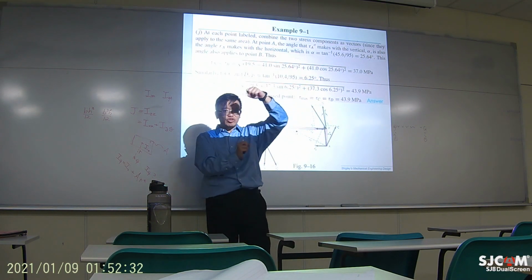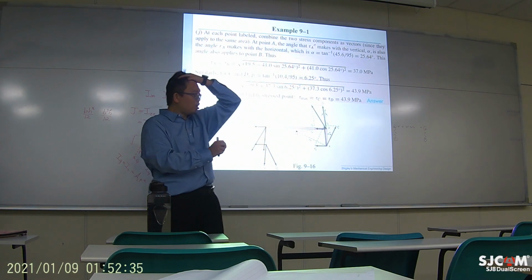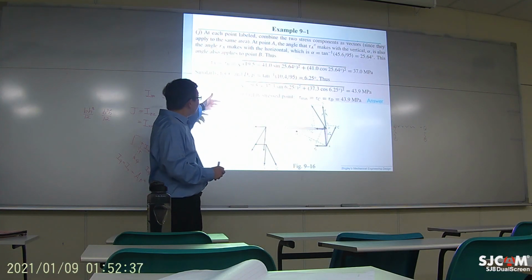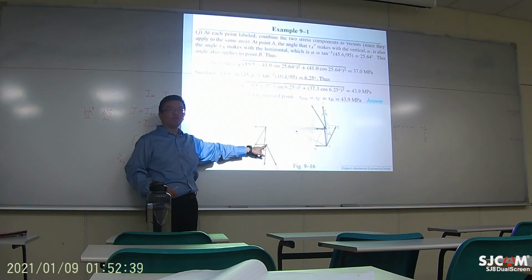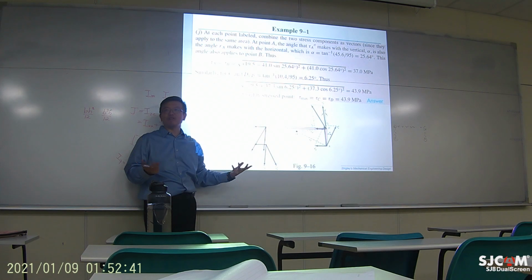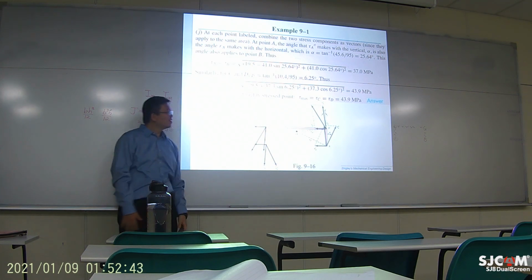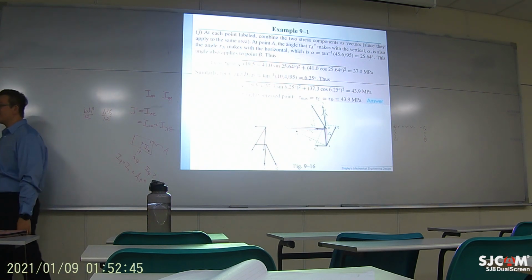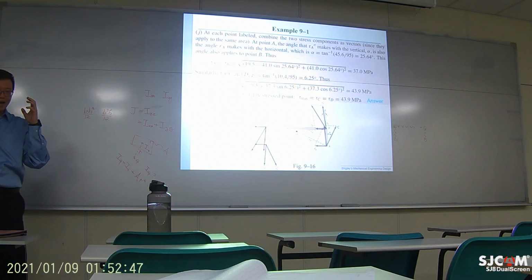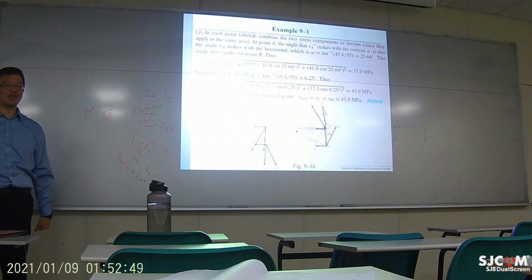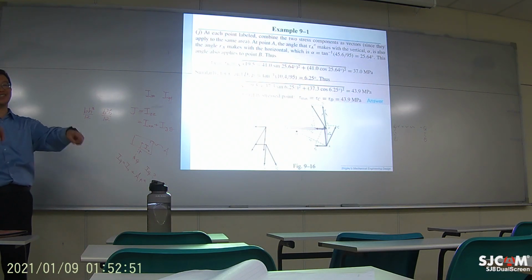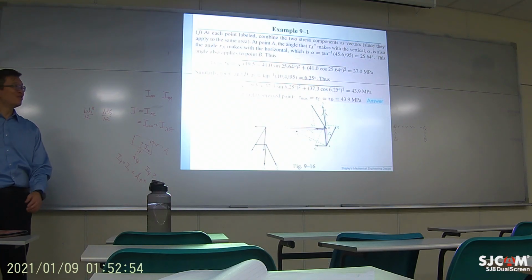Maybe when the geometry changes a little bit, or the load changes a little bit, the worst condition could be at the bottom. We don't know. Okay, so that's why you cannot just look at the shape of the weld and then make a guess. These two are the most critical. You have to truly compute for it.